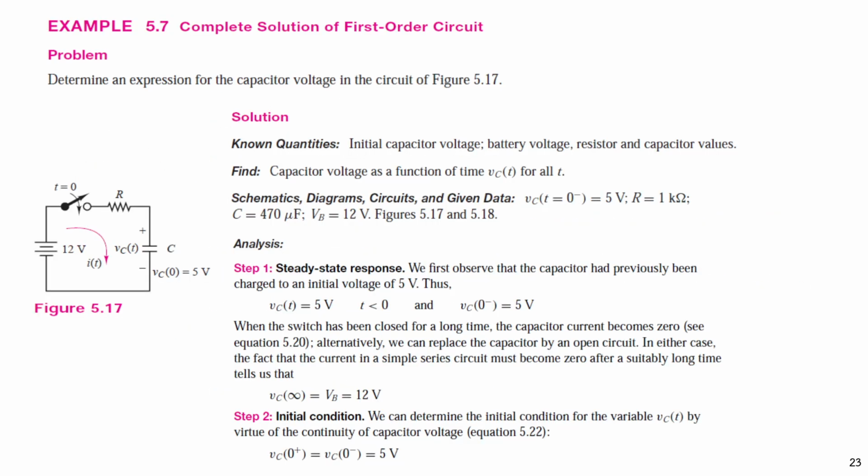And so we have time for this example. Okay, with this example, we have Vc is 0 at time 0 if the switch closes at time 0. When the switch closes, Vc is 5 volt before the switch closes. In this case, it's not 0, so there is some charge stored in the capacitor here.